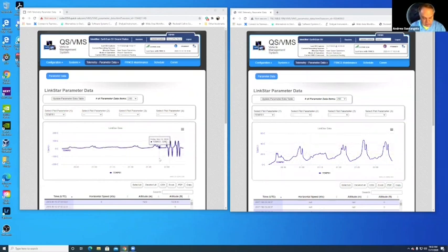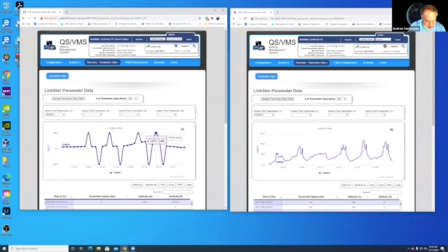But on the left side of the screen, the ground station, the data is completely changed now. This is what the operator sees. Obviously, we don't have a very long USB cord to a satellite, but on the ground, all of a sudden we notice the temperature range. Let's zoom in here. It is right around 100 degrees Celsius and minus 100 degrees Celsius. So, huge temperature swings. And as an operator, I would begin to think that something's wrong with the satellite because it's within bounds. This tells me I may have some big temperature problems with my satellite, and I may be hitting the limits of the computers, the circuitry and the sensors.